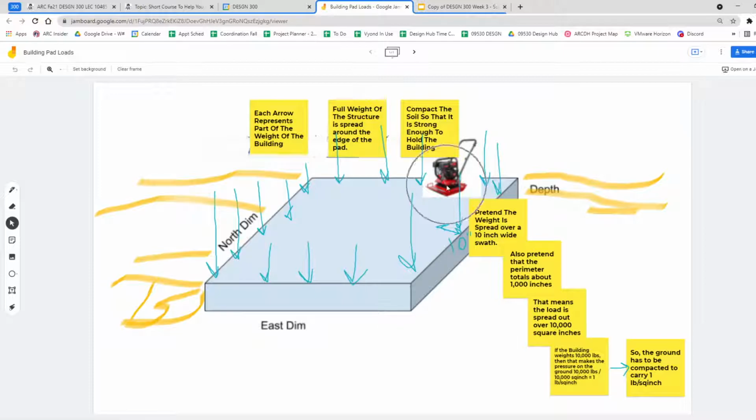And you compact according to something called a Proctor test. Have any of you read it yet? Have you gone through the reading? The whole series on Proctor test that I'm expecting you to read and to kind of think about. But this now tells you, oh, that Proctor test means that I'm finding the best compaction to do this. Okay? And once it's compacted as best as it can be, we can test it and see how it did. Okay? So that is part of the thing about dirt.